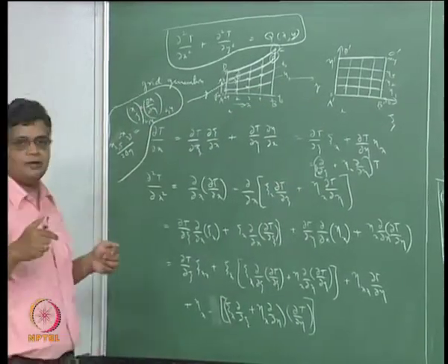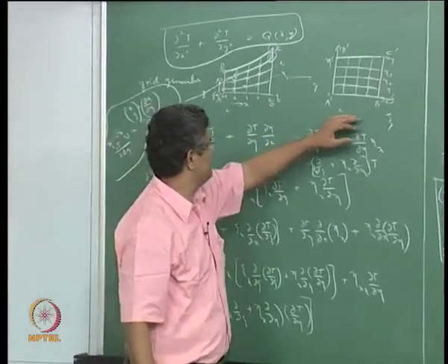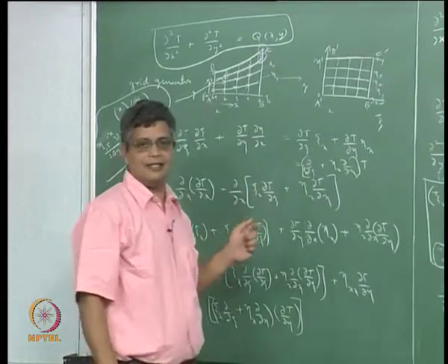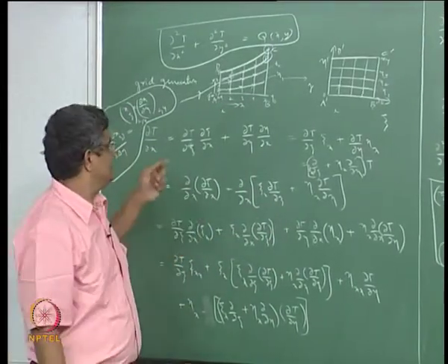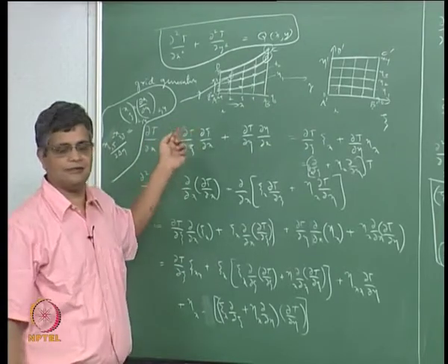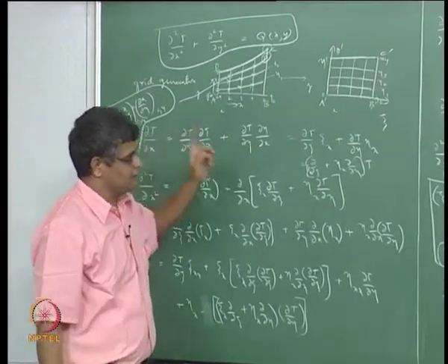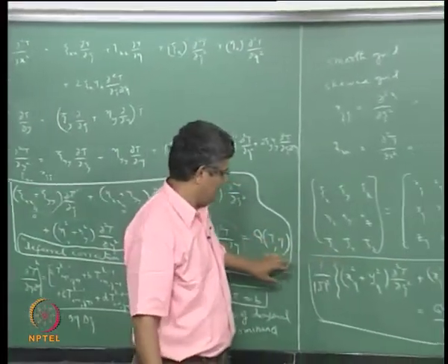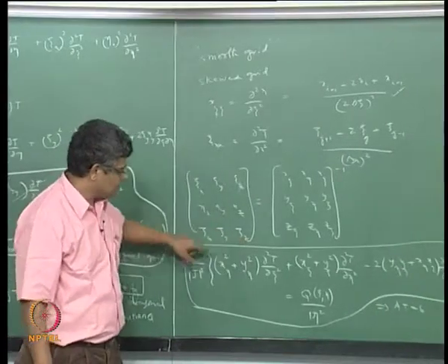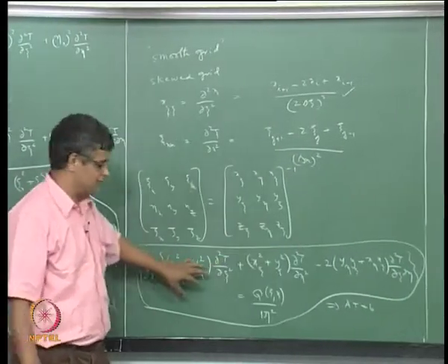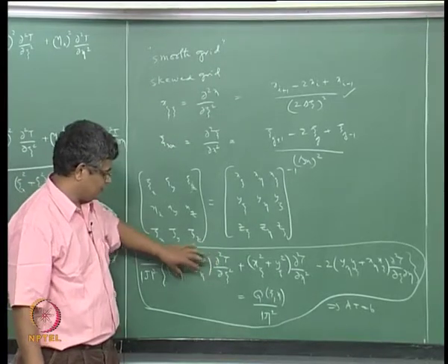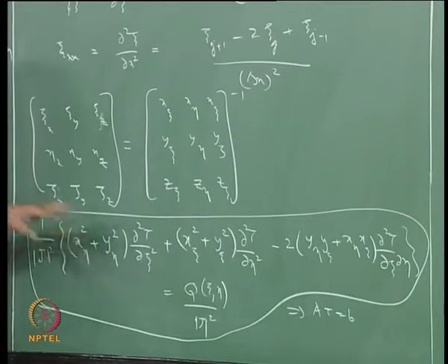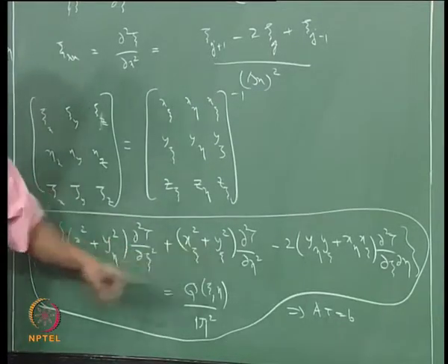So, that for a given point ij in the computational plane and the physical plane, we get psi i, eta j in the computational plane and xi, yj in the physical plane. Based on that we can derive the matrix either like this or in this way, and once the matrix are derived we can substitute them into the transformed governing equations to come up with governing equations with coefficients which depend on the matrix of the transformation, these kind of transformations.